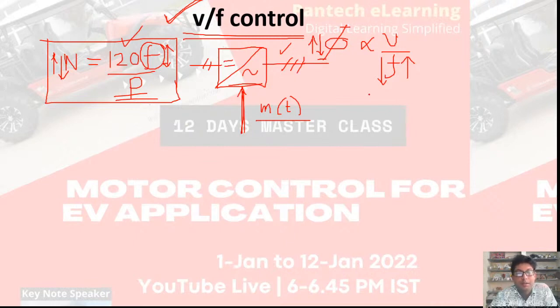Which is not advisable. So if my flux is reduced, then my machine will be underfluxed and it may not be able to deliver the rated torque. And to reduce the RPM, if I reduce the power frequency, then the flux will go up, the machine will be overfluxed, which will cause overheating of the stator coils. It may in turn cause the failure of the insulation system of the machine.